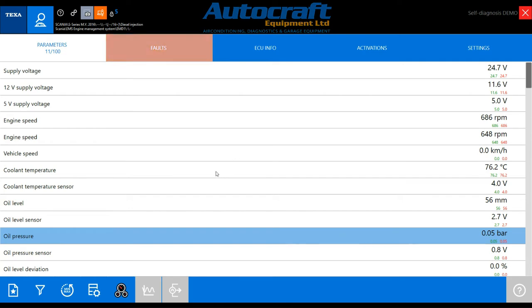And that's pretty much it. You've done all the checks you can do. You know you're getting the feeds, you know you've got your wiring diagrams, you've got your red, amber and green fault code colours, you've got symptom, causes, a repair method, everything's there for you. So with that information you should be able to diagnose and cure your fault.